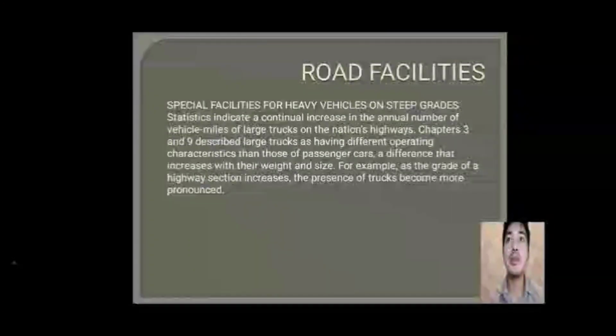A climbing lane eliminates the need for drivers of light vehicles to reduce their speed when they encounter a heavy, slow-moving vehicle. Because of the increasing rate of crashes directly associated with the reduction in speed of heavy vehicles on steep sections of two-lane highways, and the significant reduction of the capacity of these sections when heavy vehicles are present, the provision of climbing lanes should be considered.